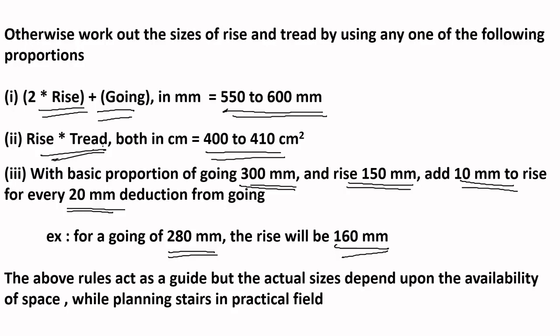So even if we have all these rules for the size of treads and risers, these rules act as a guide to help you, but the actual size depends upon the availability of space while planning the stairs in the practical field. If you have a wide space, you can go for a wide staircase. If your space is limited, you can reduce to some extent the size of the tread and riser.